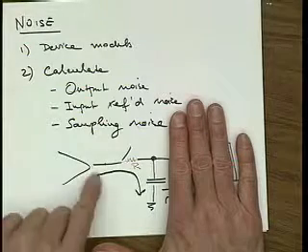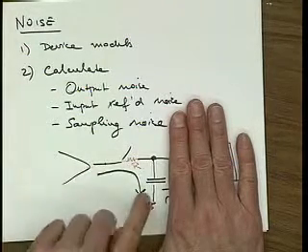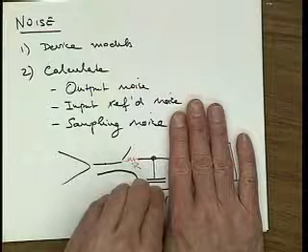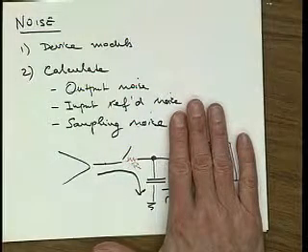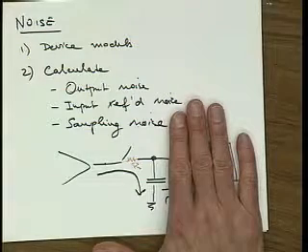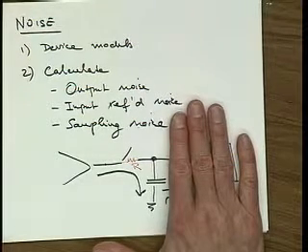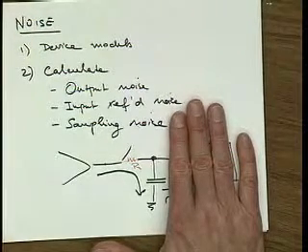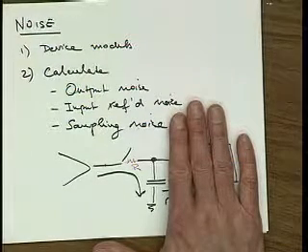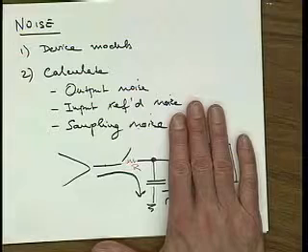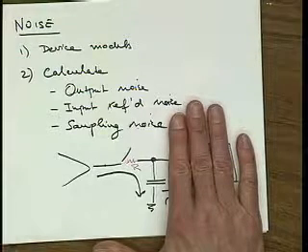And the simple fact that you can grab a signal, store it on a capacitor, and then do something more later on, that's probably the one unique attribute that made it, combined of course with the cost and the availability of CMOS, that for analog circuits, now CMOS has become the dominant technology, right?